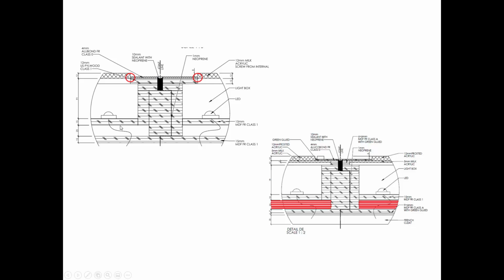And then also back here, they had these cavities where the LED lights were in, and then they just had this open space back here, and we had them fill that with mass-loaded vinyl. So get a bunch of limp mass in there. So the light boxes themselves were a weak link in the shell of this. And then this was a weak link in the weak link. But by dealing with those, we got it up to where it wasn't too detrimental.